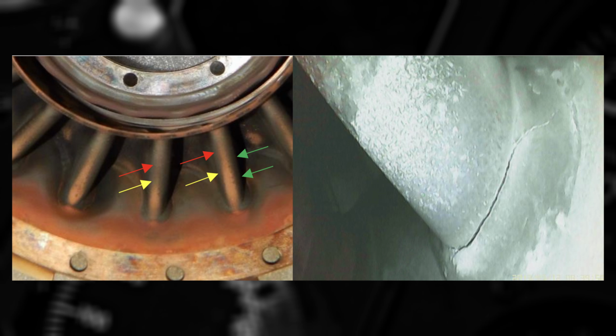Routine cleaning keeps the buildup of material from creating or covering potential issues, and inspection by borescope tells you how well your cleaning technique is working. Blocked cooling holes of the nozzle guide vane, or NGV, results in thermal damage and cracking.